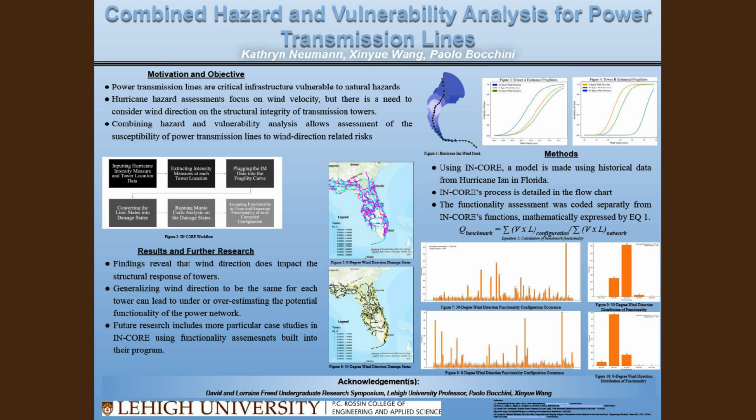Since this data is quite large in scale, a linear interpolation model was employed to return a more varied max wind speed between the centers of the hurricane and the edges of the polygon. The tower network was created using power line data of Florida and assuming a tower density to place towers every 500 meters. This resulted in approximately 63,000 towers to be considered for failure.